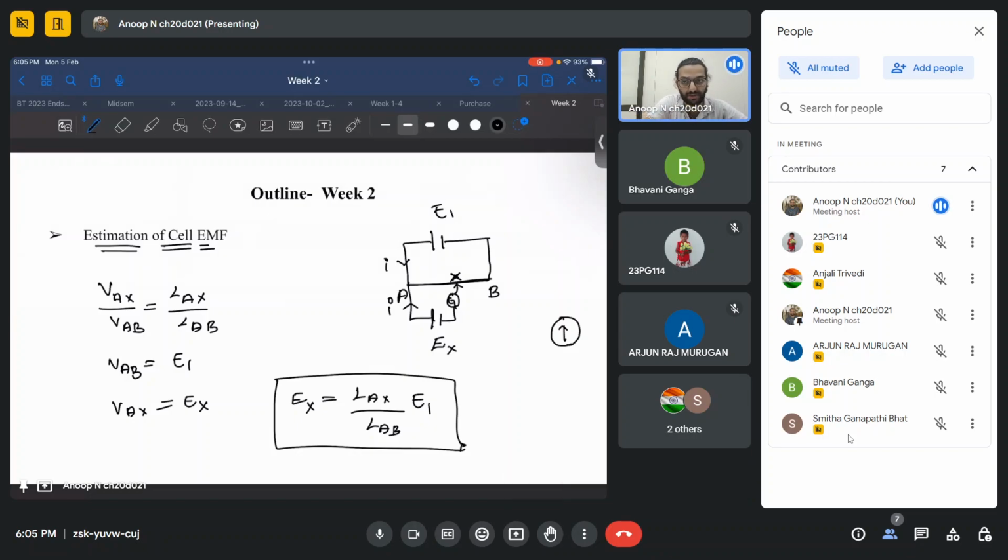So this we have actually done. You might have seen that on a scale we have a high resistance wire, which is stuck onto a simple measuring scale. From there, we connect a known cell of some voltage, suppose 2 volt or something. Then below we have the unknown cell, a second battery.